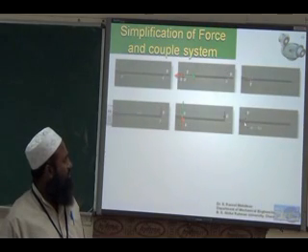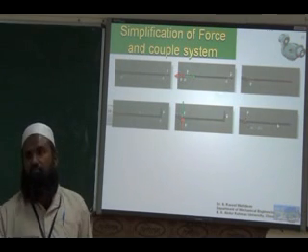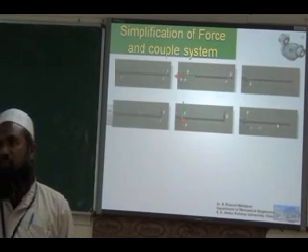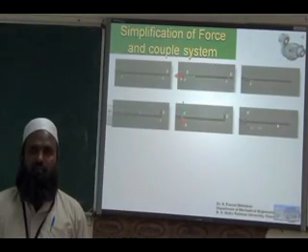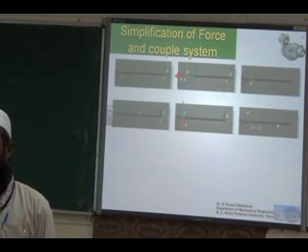So we have a force at point B as well as a moment developed due to the couple. That moment will be equal to F times d, the distance between points A and B. So if you try to transmit a vertical force from point A to point B, it will introduce a moment also.